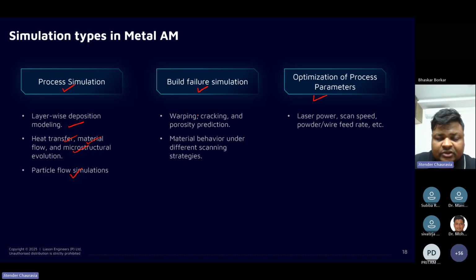Then when the build failure simulation comes, there your main concern is residual stresses, whether you are exceeding yield strength of the material or not.